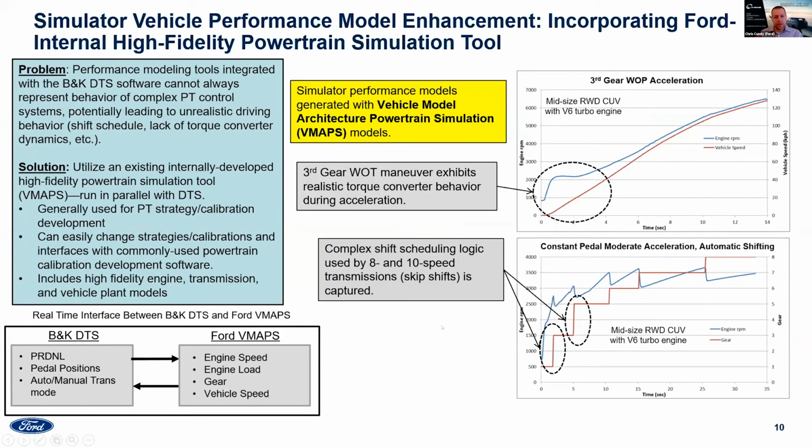The last thing I'll talk about is performance modeling. And so we did run into some limitations very early on in this process with building free driving models and getting realistic driving behavior. So with some of the more complex powertrain control strategies and torque converter dynamics, these couldn't always be represented well with the included simulator performance modeling tools.